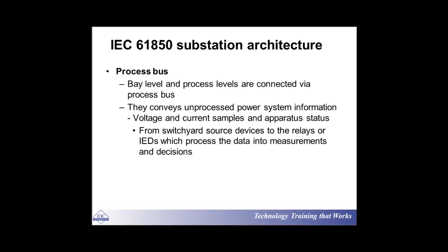You are talking about substation automation, right? So you should be aware of the status of the circuit breakers, and be able to remotely control them. Even at times, if your disconnect switches are motorized, you should at least understand the status, whether it is open or closed, and if they are motorized, remotely open or close them. But at least the status is important.